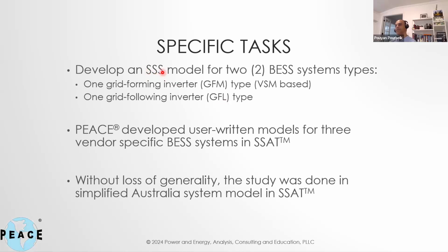I'll talk about that in a second, what that means. This is forming an explicit small signal model, so a state space model, for these grid forming converters and these grid following inverters. So we took both types.